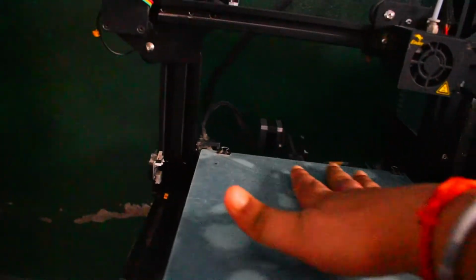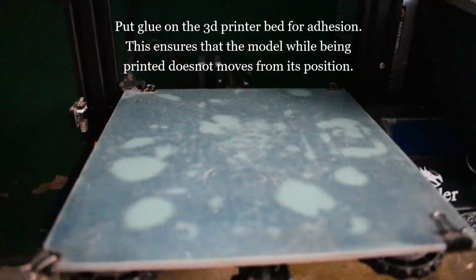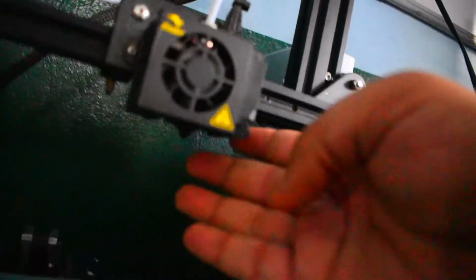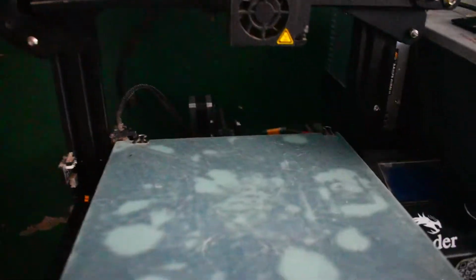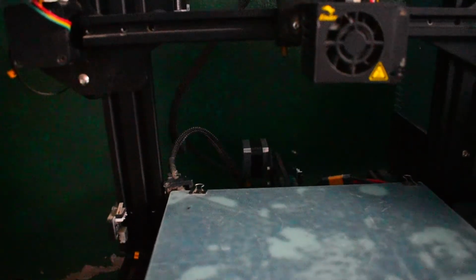then what you have to do is put glue on the surface of this whole bed, so that when this nozzle moves, so here the nozzle is, right? This 3D printer's nozzle ejects this material in molten form. When this nozzle moves around this bed, the material has to stick to the bed. So if you don't provide the glue, it will not stick and your model will be distorted, whatever it is printing. So for that you have to ensure that you put the glue.